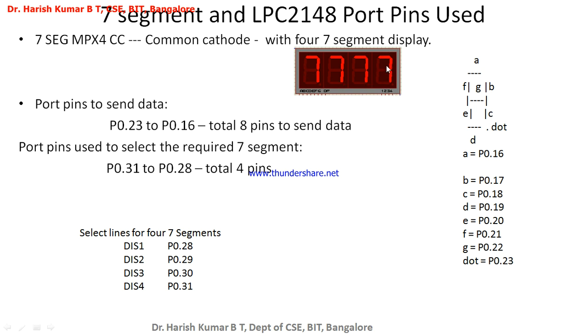Now if I want to select all of them, I have to give 0 0 0 0 here. If I make all four 0, all 4 will be selected, and whatever data you give here, the same thing will be displayed on all the 7 segment displays.